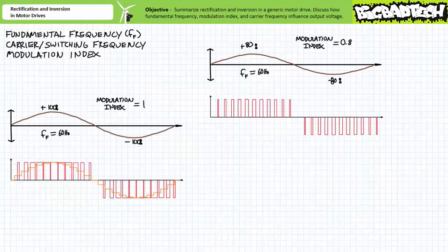The section centered at 15 degrees would have a median value of 0.207 of peak value. The section centered at 30 degrees would have a median value of 0.40 of peak value. The section centered at 45 degrees would have a median value of 0.566 of peak value, and so on. Given the duty cycle for a particular section still influences the average for that particular section, and the fact that duty cycle has been dialed down to 80%, the output is therefore proportionally reduced to 80% of maximum.